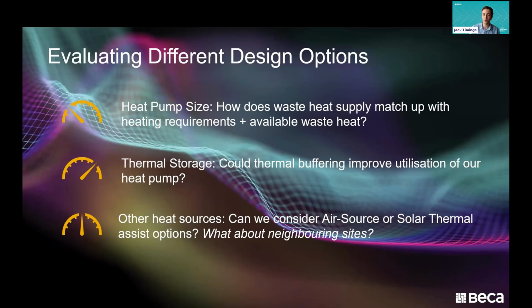Then we had a look at thermal storage. Because this was something that was really going to help this project, because a lot of the time the refrigeration plant and the hot water system weren't working eye to eye. They were operating at different times of the day. We had waste heat, but we didn't have a use for it, or we needed hot water, but there was no waste heat to access.